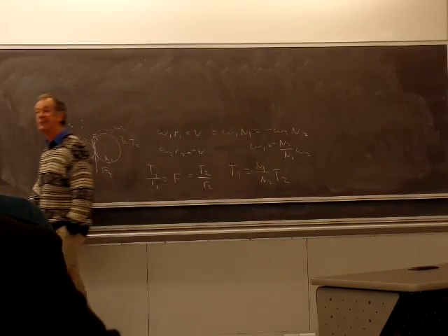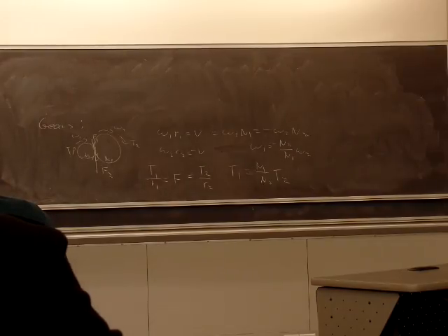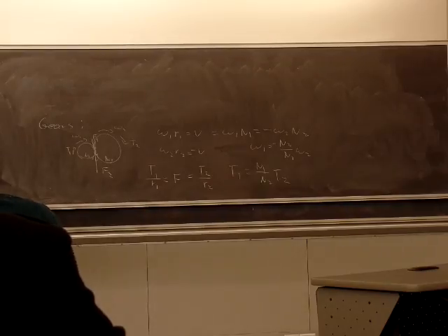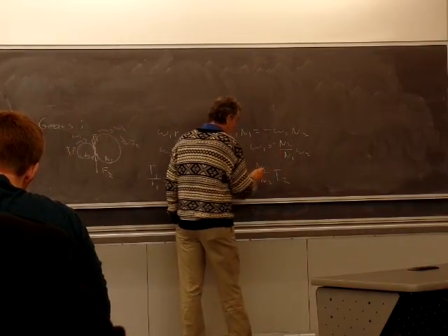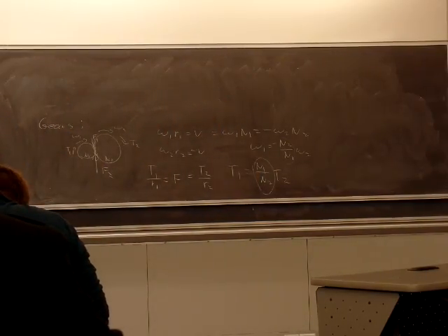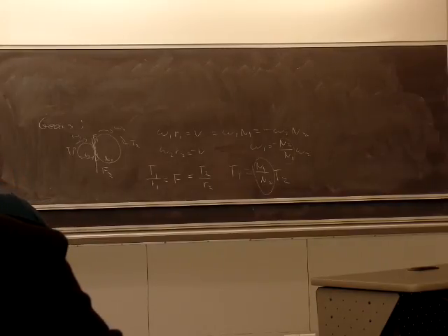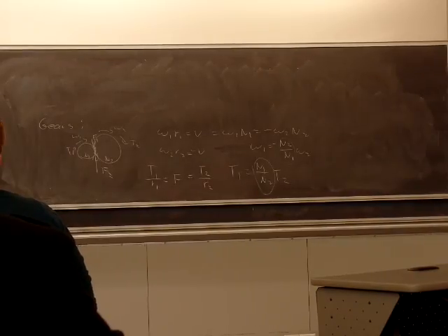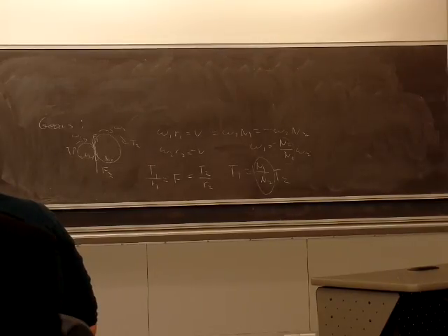Got that. So, notice the relationships here. Omega 1 and omega 2, and T1 and T2, right? In one case it's minus N2 over N1, the other case is N1 over N2. How do you describe that? The inverse relationship? Inverse, it's a negative reciprocal, as a matter of fact. The negative reciprocal. That's always going to be the case.